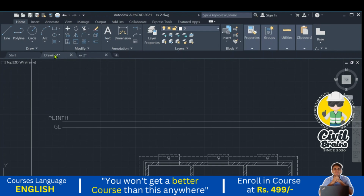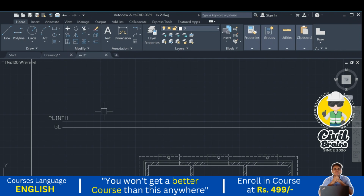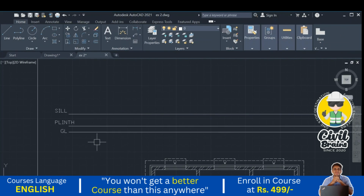After the plinth, what is the next level? That is sill level, 0.9 meter offset. From the plinth it is 0.9. Okay, I just write sill, then offset.